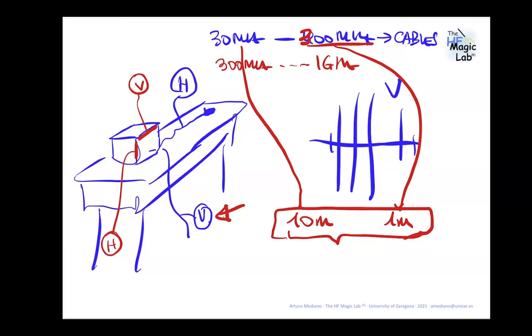To be in the far field, I need to be 3 meters divided by 6, so at least 50 centimeters of distance between the antenna and the product. So no, I am not doing a good far field measurement, but this is the way to do it on top of a table. Great, thank you.